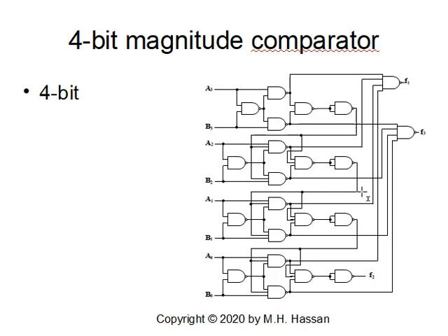See, the feedback will be the last. So those 3 NAND gates will become a 3-input NAND gate. The feedback that we take here goes to that set of 3-input NAND gates. Here there's a short circuit. The same thing, we took the output. The circuit is fully verified and tested, fully implemented in hardware, and is a fully correct circuit.